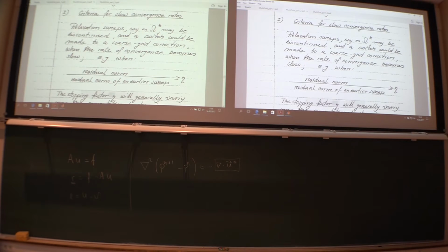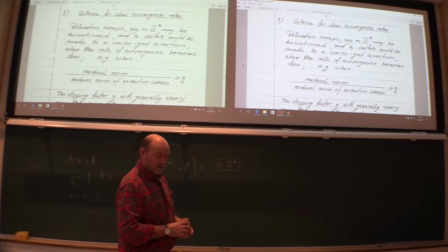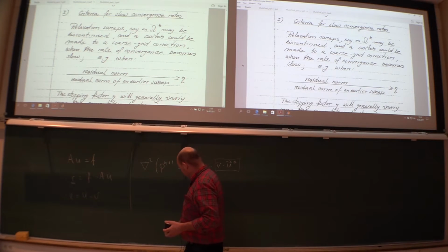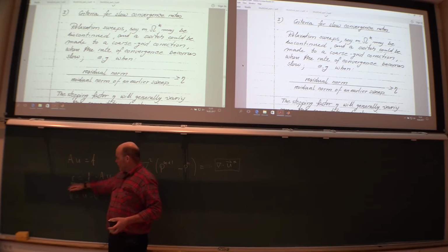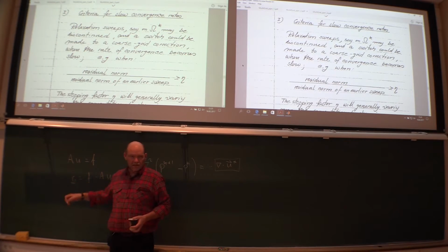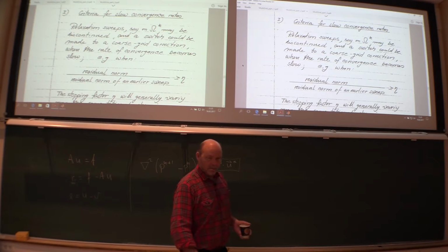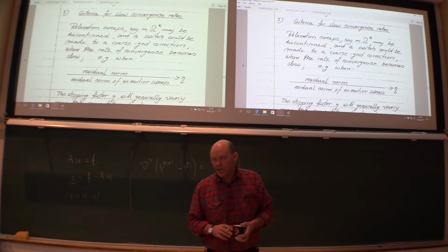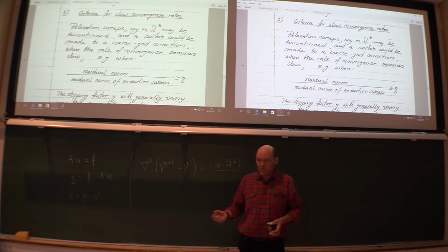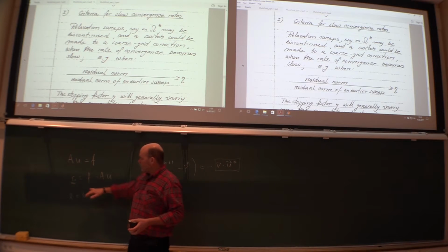But typically here, you just look at the residual norm. Also, I remember one version of Fluent, an old one. They did it very dangerously. They took the first iteration, or the first time step, calculated a residual 0, and then used this one as a scale for the next 10 million iterations that you were going to need. So the residual that it actually printed out on the screen was non-dimensionalized with the first residual.